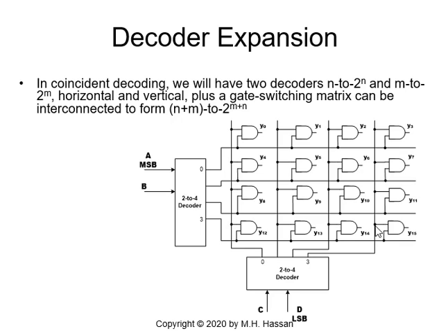And the intersection of those two, we take to an AND matrix to generate all outputs, which are active high or could be active low. Change the matrix to NAND gates and they are active low. So in this case, we are looking at active high expansion.